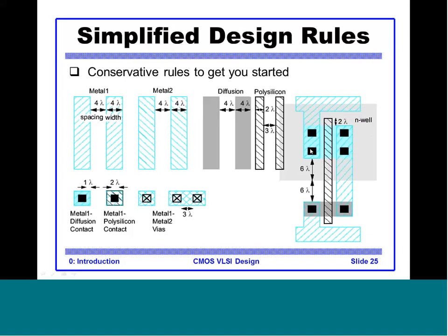The contacts here are source and drain contacts. Both the drains are connected together. If you see on the NMOS side, this is the source, which is tied to ground. These are the diffusion regions. Again, this drain is connected to the PMOS drain. Again, diffusion regions. Sorry, this is the diffusion region. Again, the source of PMOS is connected to VDD here.